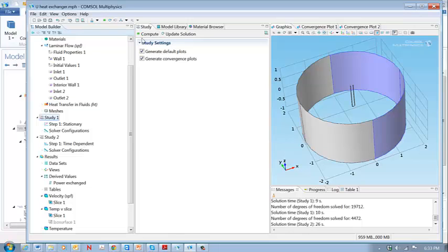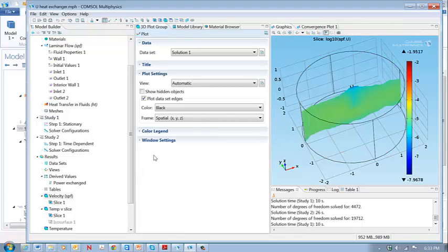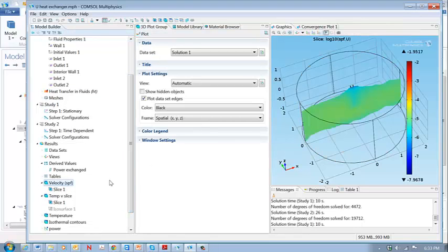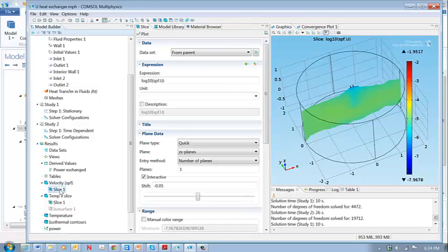So we can run that now. It runs pretty quickly. And what I think is a good idea is to check and just make sure that the velocity is going in the X direction. So what we do is we've got a plot here. It's a slice plot with the XZ plane. So this is in the X direction. And if you just plot